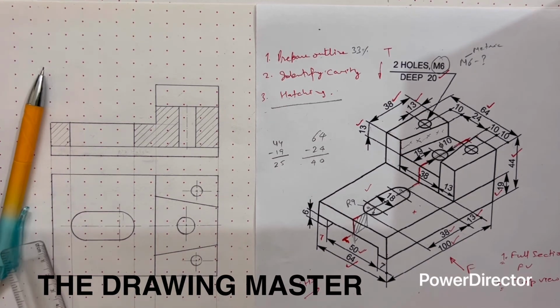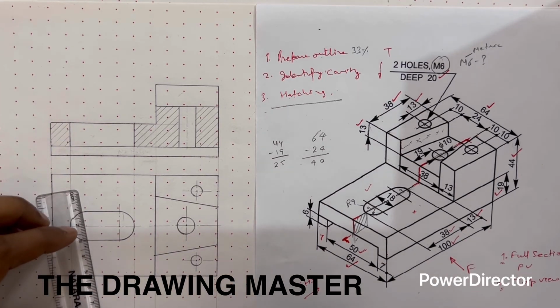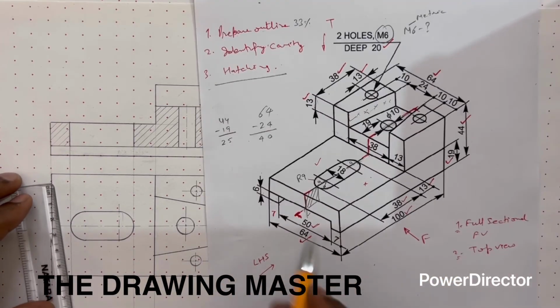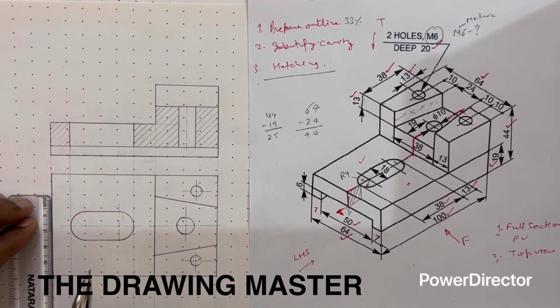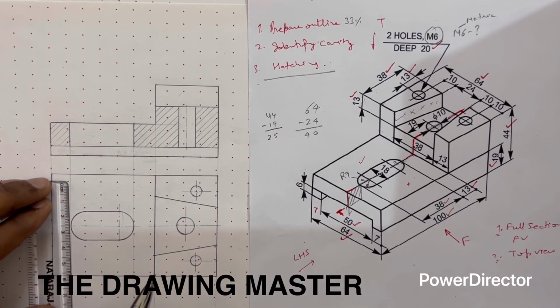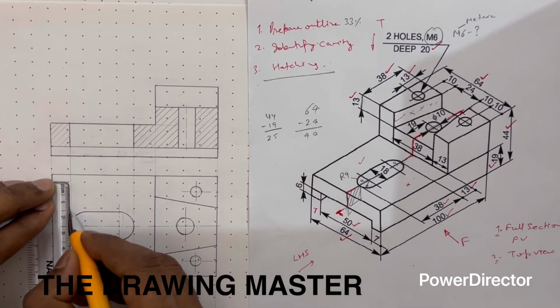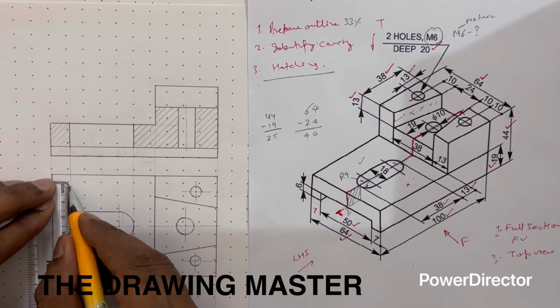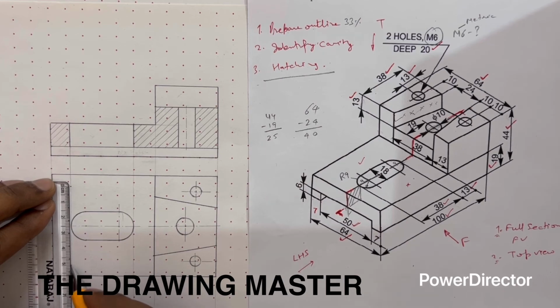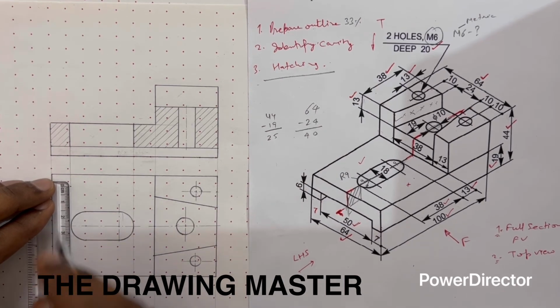So now this is the top view of the object. In case you want to draw the hidden lines, only this line will be hidden here. From the center, we can measure 25 upside and 25 downside. This is 5, 10, 15, 25 this side and 25 this side, meaning total is 50.